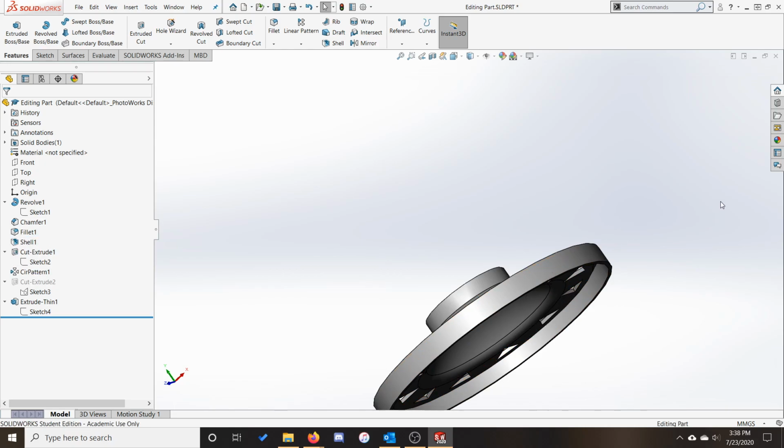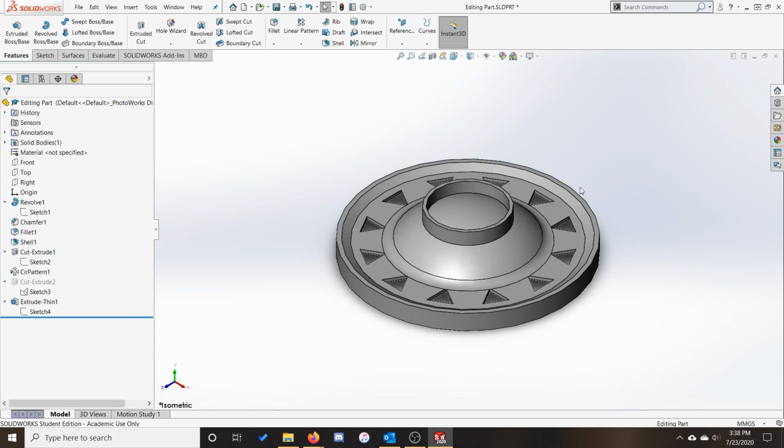Great, okay. Last but not least, I want to add a big brim to the front. I've been told that's peak fashion these days. I'd really like for it to be a part of our shell, but I don't want to accidentally make any dependencies before I move it above the shell feature, so it would be convenient if it was made before the shell was created. For this, we can use SolidWorks' user time machine, or the rollback bar as it's formally known.